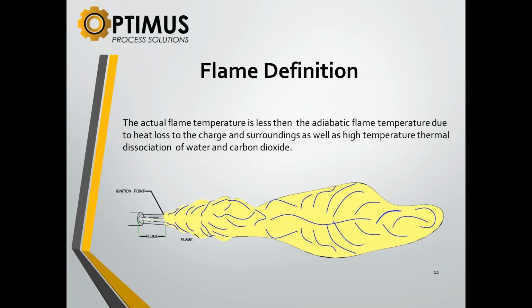So is dissociation beneficial? Well, it's one of the differences between adiabatic flame temperature and real temperature, because once that breaks down, that hydrogen burns after the flame. Wow. Okay. So even though it's an insignificant amount, it affects this theoretical flame temperature called adiabatic.